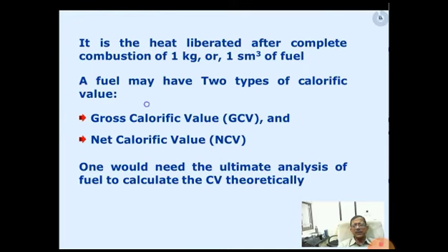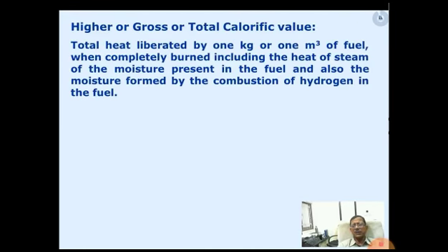So suppose we have an ultimate analysis of the fuel. The gross calorific value is basically the total heat value. That means all the combustible components of the fuel are reacting with oxygen in complete combustion reaction, and the total heat that is released, even including the heat that is actually being taken away by the water which is forming steam, including that heat will be the gross calorific value.